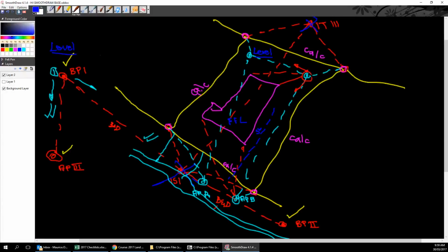So we can set up our instruments here, observe down to here, observe to here, make sure the marks haven't moved, and we know exactly where we are. Then we can start doing some as-built shots on these sewer lines, determining where they are, how deep and at what level, so that it can be used for council records.